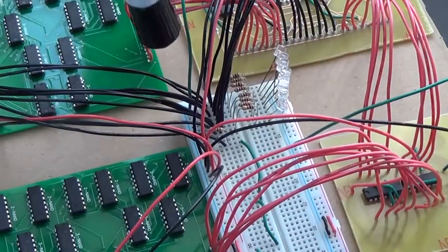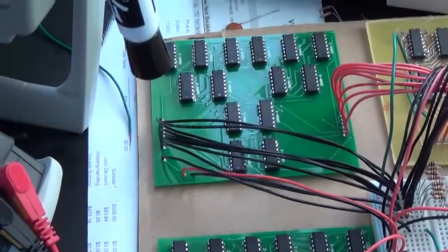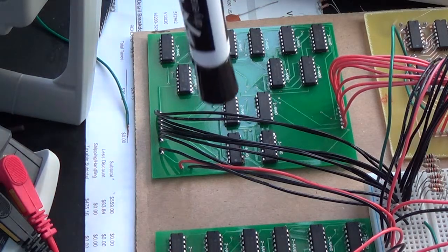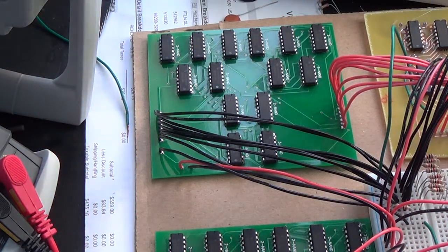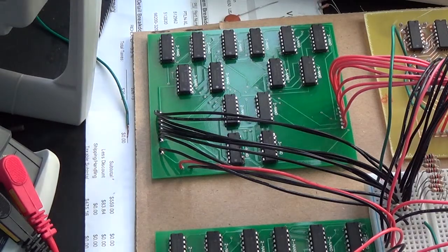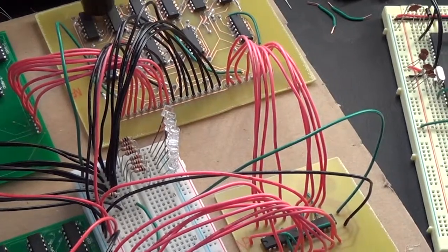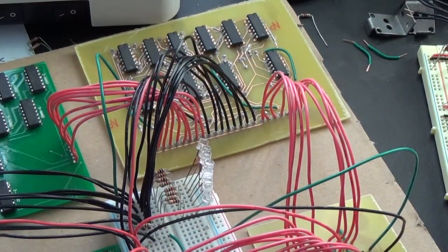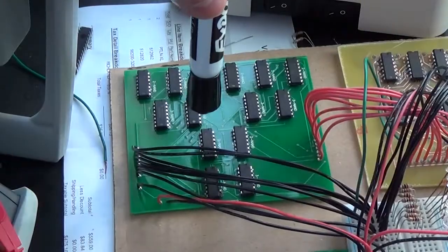But it also goes back to the input of the A register. So each time I pulse the A register enable high, the A register will accept the sum at data into the register. Then Q, which is going to the input of the ALU, will reflect what the previous sum was, and there'll be a new sum waiting at data for the A register.